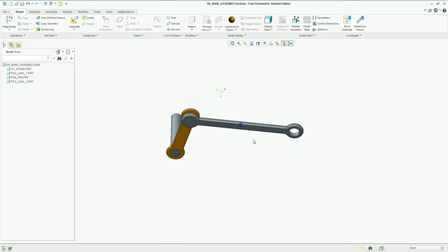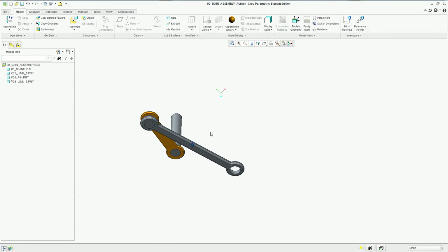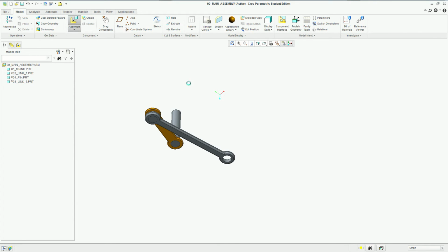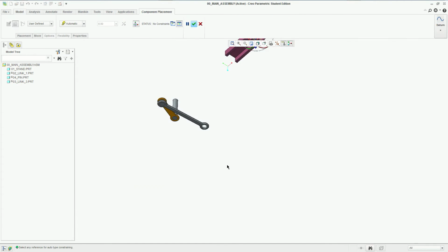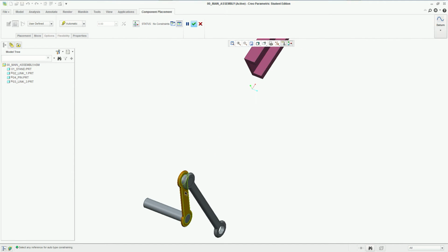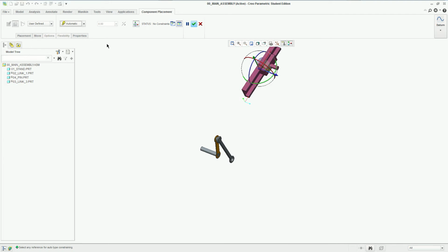So this is how we want it to work. This is good. This is dandy. Now I'm gonna bring in the subassembly that we made. I'm gonna say bring in the slider subassembly, and then I'm gonna place it using the distance constraint. Now here is where you use the physical location constraints right here. Remember from the previous videos, this is the behavior constraints, and these are the physical location constraints. And if I'm trying to place a subassembly, I'm only going to be using these physical location constraints. I'm not going to try to use any of this. Unless it applies, then definitely go ahead and use it.